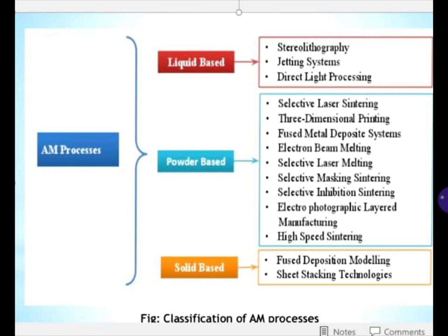And in the solid based techniques we are going to use solid polymers, solid ceramics, or metal matrix composite material. Here we are going to take the solid material, fuse the material, melt the material, and then deposit that material layer by layer in order to create the 3D model.